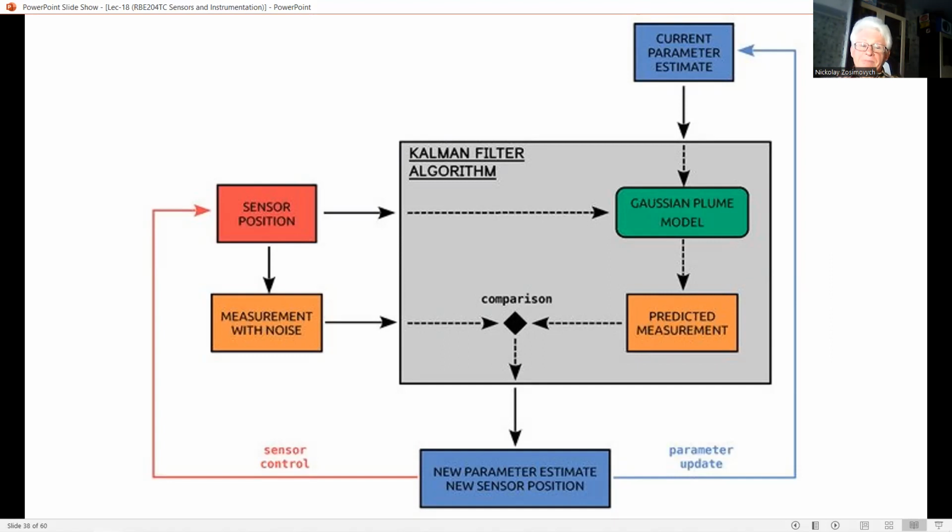This predictor step uses the process model and the covariance matrix of the input disturbances, including model error. And second, correct the predicted variables and the associated error covariance matrix. This is a posteriori estimate. This corrector step uses the measured data or output measurement, output relationship, and the covariance matrix of the measurement noise.